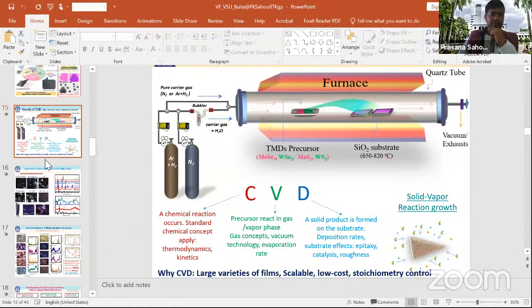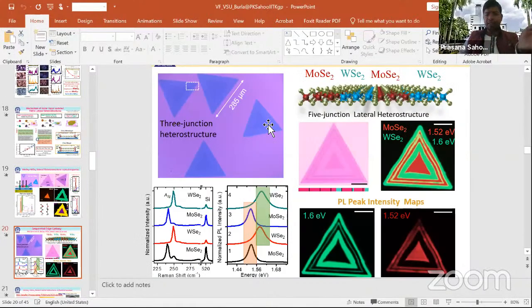Yeah, by the way, I forgot to mention that because I was in a hurry to wind up the talk. These are basically PN junctions. Molybdenum behaves like N-type material, tungsten behaves like a P-type. That means a simplification is that we are directly growing PN junction diodes. We don't need to physically or chemically modulate something. We can directly grow a PN junction. That's why it is a step further.